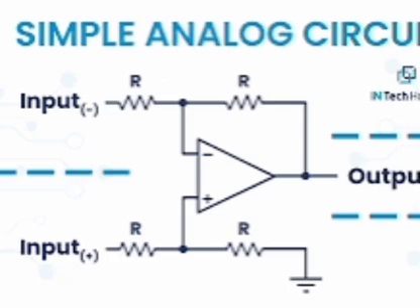Maximum value of current, IC max, equals VCC by RC, taking VCE equal to 0 at saturation. This is the ideal case. Power dissipated in the transistor, PD, equals IC times VCE. Power dissipation is maximum in the active region and minimum in the cutoff region and saturation region.